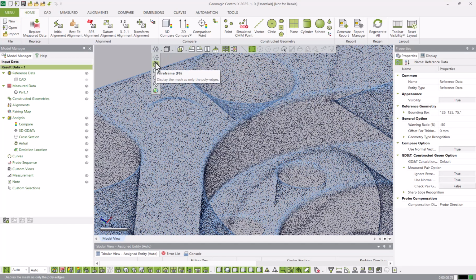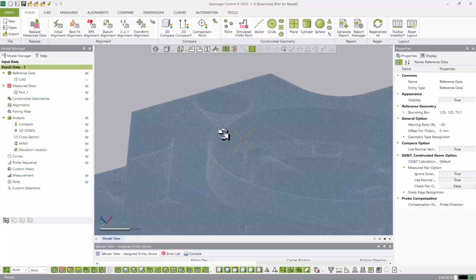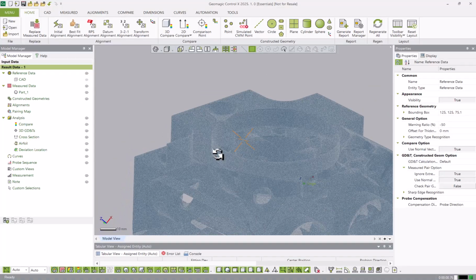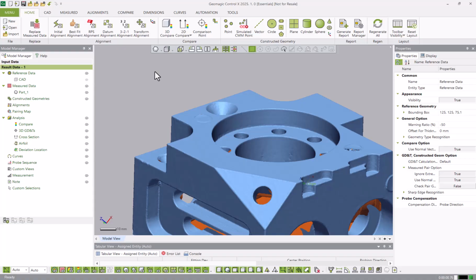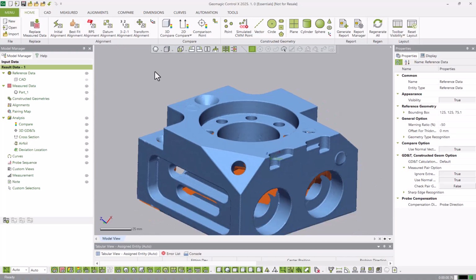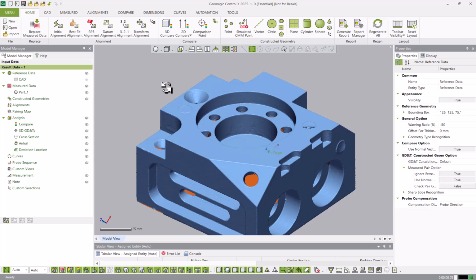The second option likewise is a transparent wireframe. You can see that the body would show the triangles, but it would not shade the edges. This third particular method of rendering is called shaded without edges. This is going to be the most commonly used rendering method, in which the triangles are shaded but the edges are not displayed.